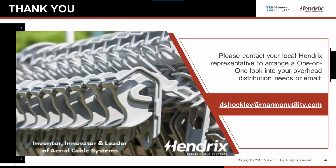That picture is just taken from a particular utility that's just their standard. Anytime they're going over a roadway of any size, they double up on the spacers. It's really not required. If y'all want to buy more spacers, that's fine with us, but it's really not needed. But from a sag and tension perspective on the phases, it's all 30-foot spans.